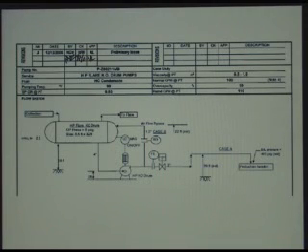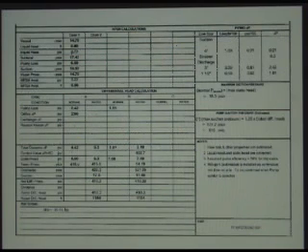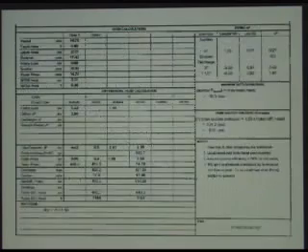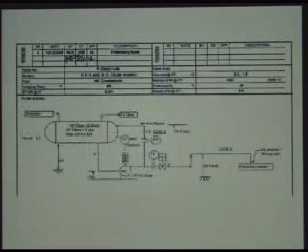Now this is the most conservative setup right now in that you don't get any credit for the liquid level that's inside the tank. So we're assuming that we have to be able to pump this tank completely dry, or we're not sure where that level is, so we don't take any credit for it at all. So that means that the liquid head, 8 feet, using the specific gravity, is 2.77 psi. And so you end up with 17.47. Now here's your piping losses. And that's the friction loss in that 4-inch line that runs to the suction of the pump.